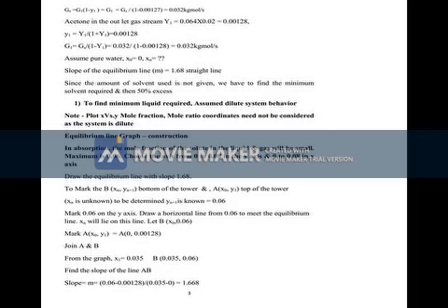Here I have shown the arrangement in which the bubble caps are arranged on a tray. So I think now you refer to it and go through it, then it will be thorough. Next we have to find what are all the parameters given. This is the liquid flow, gas flow rate is given. Then the concentration of acetone in the incoming stream is given, and how much acetone is to be removed is given.